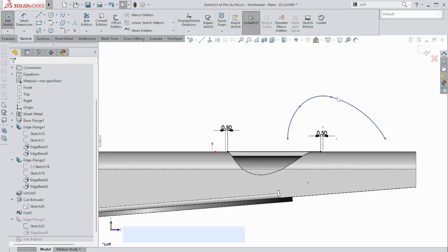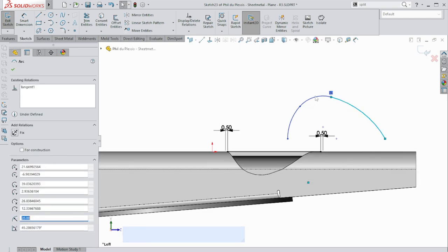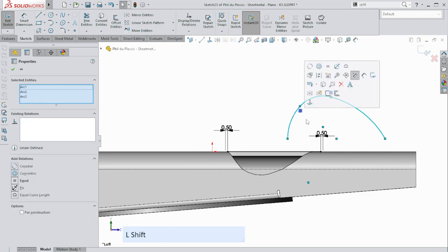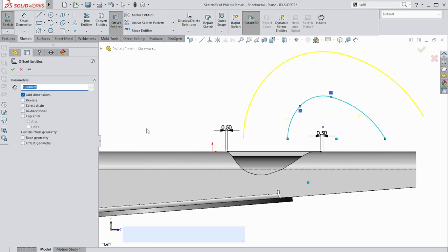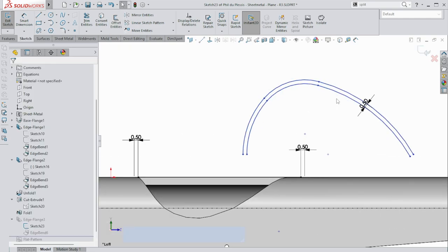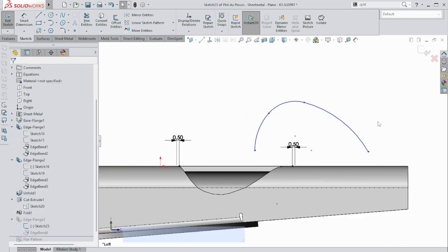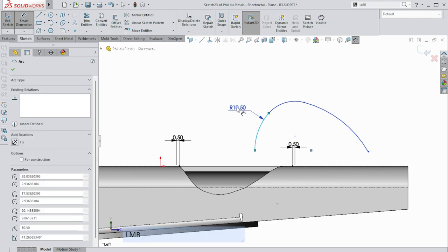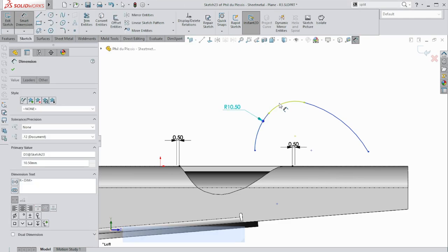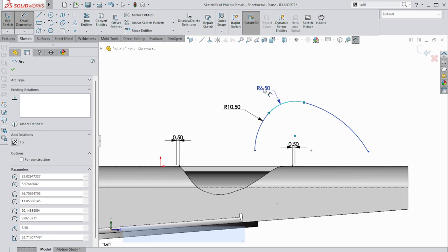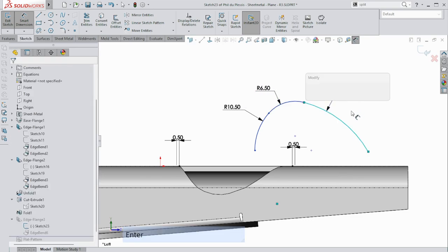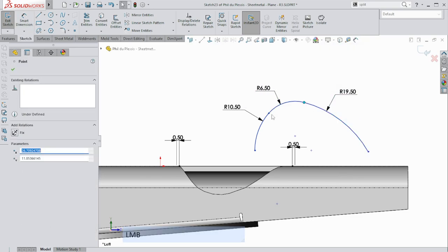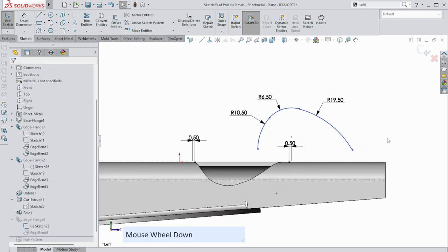So you can't select and move because it's going to only move one point. But before we move it, remember this is larger than what we need because that's the cutout. So we need to offset this lot by 0.5 inwards. So let's go inside. And in fact, I probably don't need this outside sketch anymore. So just to control things, quickly give this dimensions. I'm just going to hit my enter button to speed things up and just make sure that these are tangent. So that gives me some degree of control.